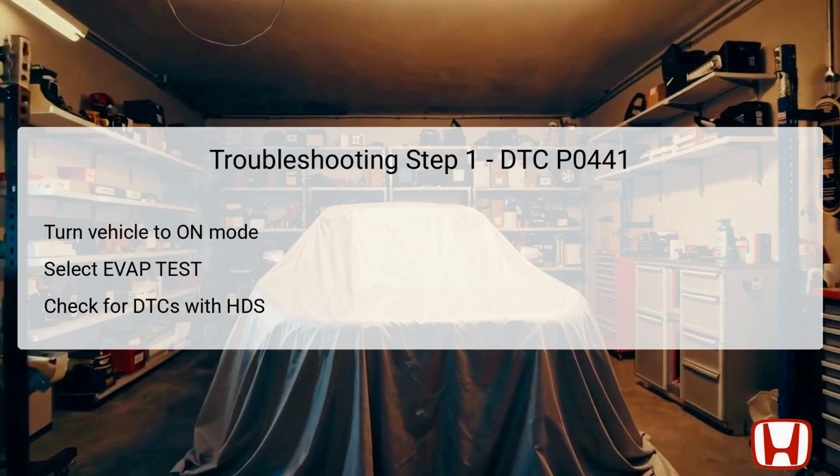In the first troubleshooting step for DTC P0441, begin by turning the vehicle to the on mode without starting the engine. This mode allows access to the onboard diagnostic system. The next step is to select the EVAP test function from the menu using the Honda Diagnostic System, HDS, which is a specialized tool designed for accurate vehicle diagnostics.